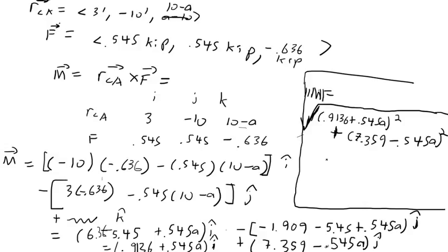Okay, the question is, why did we apply a force of 1 kip? I am doing what I might call finding a unit moment. The distance will be minimized wherever the moment will be minimized, not where the force is 1 kip. So for simplicity, I gave it a force value of 1. You can pick any number of your choosing. It'll turn out exactly the same in terms of minimizing a.